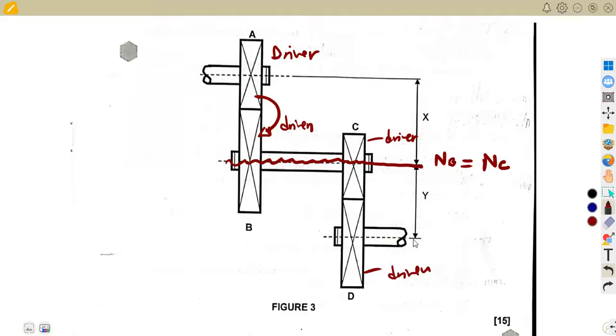All right, we're not going to waste much time on this question. They gave us that the system consists of the input gear A with 28 teeth. So on gear A, we're given the number of teeth, TA, which is 28. No problem. All right, guys, let me write this. We are going to need this information aside. And 850, which is the speed. If you take a look back at our diagram, it was 850, not 8,500 revs per minute.